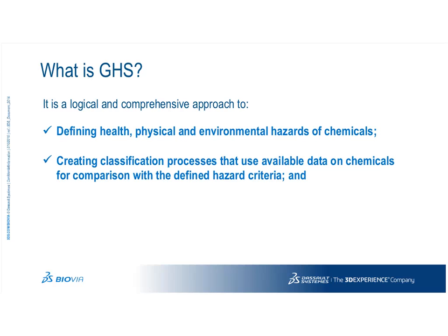Just an example, if I was talking about butane, it's a highly flammable material. We know that. Here in the U.S., we use the Hazardous Materials Identification System, also known as HMIS, which really looks at a couple key characteristics, things like flash point and vapor pressures.